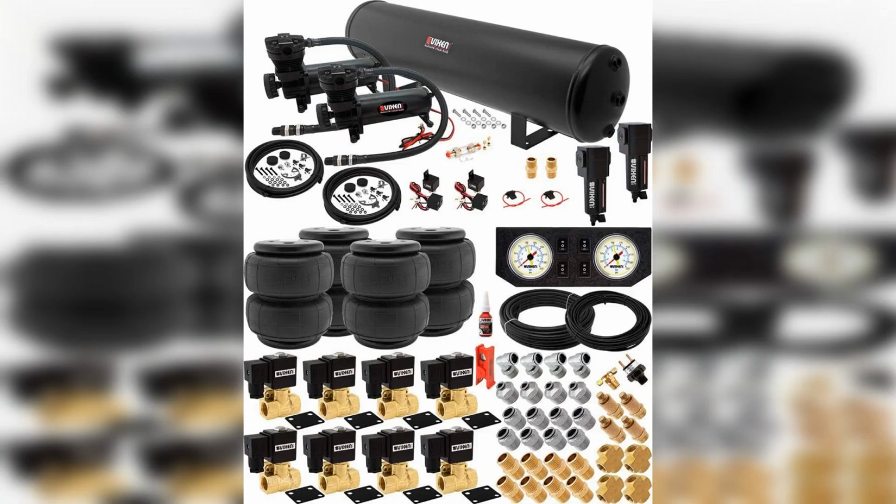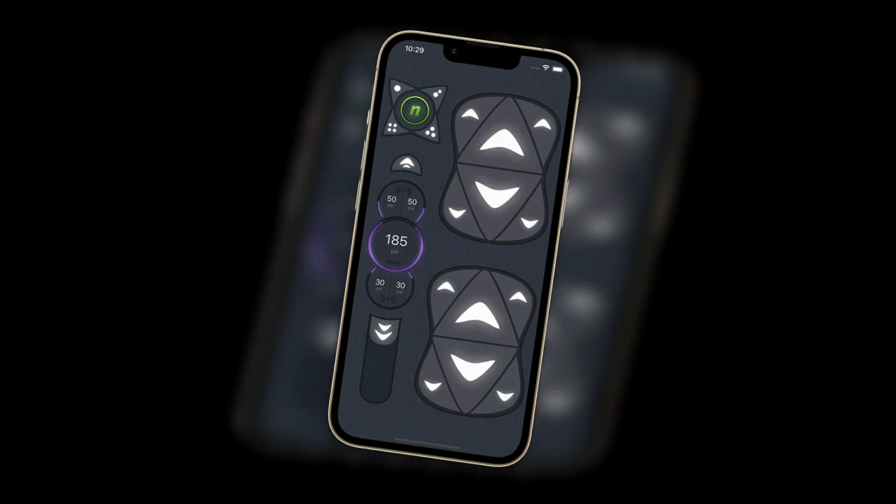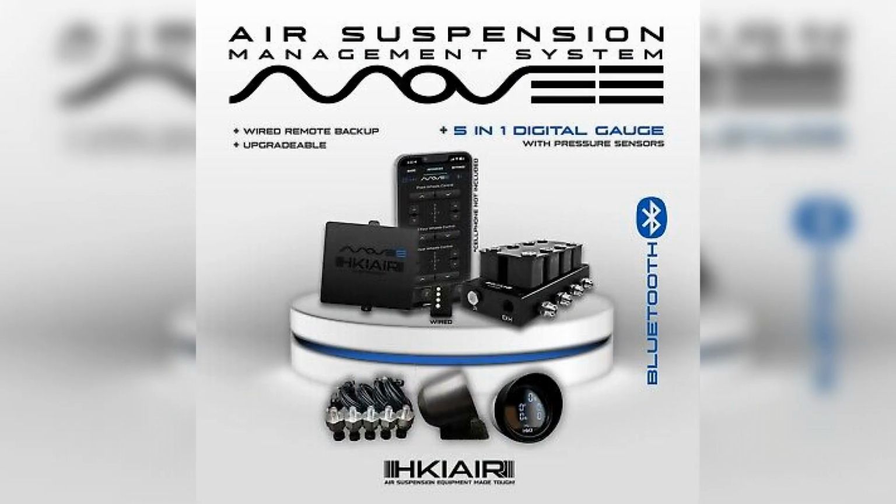The main role in the entire suspension operation is assigned to the pneumatic elements, which consist of a housing with a guide, a cuff, and a piston. Cuffs are made of durable elastomer. Structurally, the pneumatic element can be made together with the shock absorber or installed separately. Features of operation, advantages and disadvantages. The main disadvantage of air suspension is the high cost of manufacturing. Otherwise, modern systems are quite reliable.